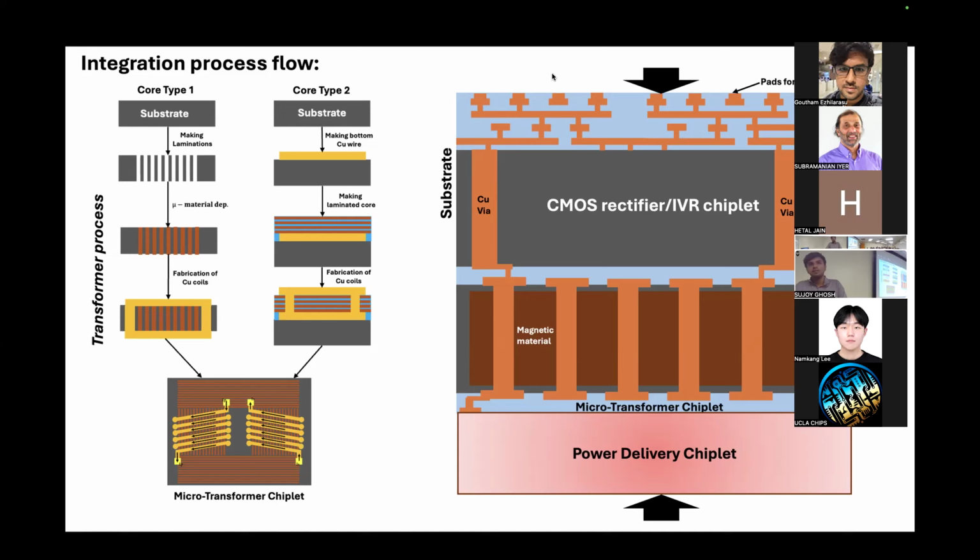One thing is we are limiting ourselves to using only silicon-like processing techniques. We don't use any packaging. For example, you can make your wiring much thicker if you use something like a PCB, and you can laminate these very easily with polymer, right? Correct. So if you were to make this dielet with a polymer backend and then bond that transformer chiplet to this, you may get a better result in my opinion.